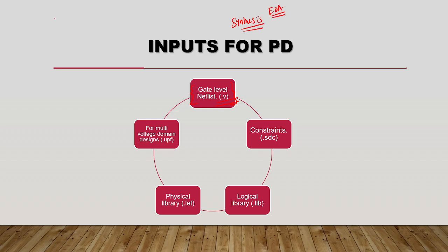EDA tools, in the front end, you have some EDA tools like Synopsys tools, Cadence tools, and AMD Xilinx Vivado. For verification you have the Jasper tool and Questa Sim, and for Verilog you have ModelSim. Quartus Prime, all these are nothing but tools. What they will do is synthesize and convert your code into a gate level netlist, which is nothing but hardware.